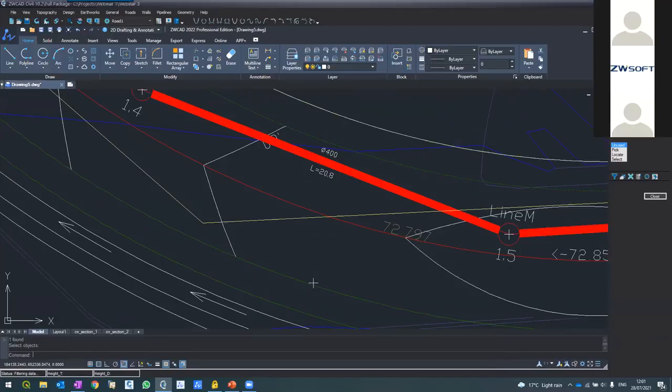Now, I don't know what the depth is, but the electricity company told me that the average depth is 1.2 meter. So I change this to depth, and I'll put here 1.2 meter. And since I'm working in millimeter, I know that it's a 150 millimeter pipe.